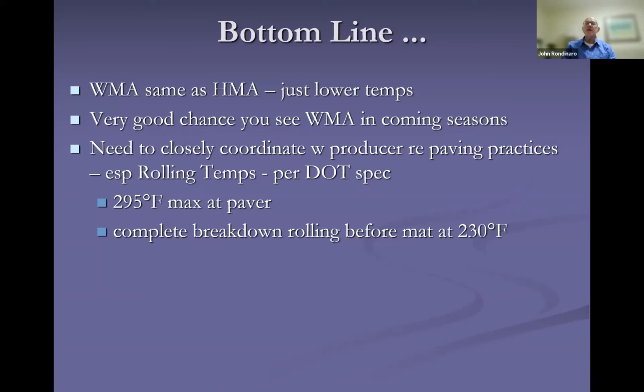The key here is if you are working with warm mix, you're going to need to closely coordinate with your producer, because there are a couple key characteristics or factors that you need to take into account in your paving practices. And this is especially regarding roller temperatures, because as per the DOT spec, that material is 295 at the max at the paver. That's the warm mix.